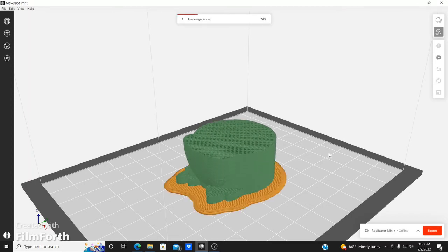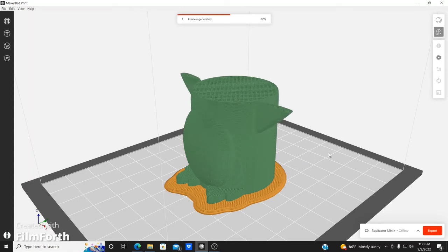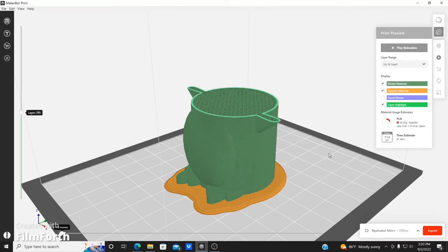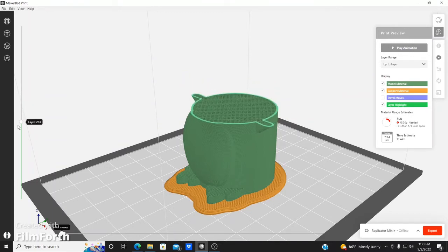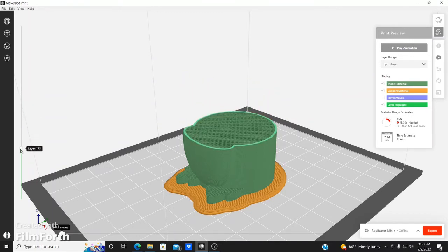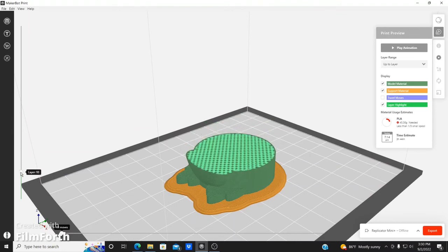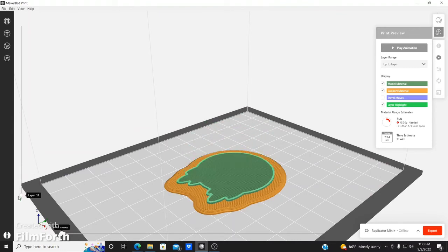There you go. So now this is what it looks like from the tool path and how it's being generated in a simulation. On the left, you have the scroller. You see layers of 295. If I was gonna do the entire full layers, it'll give me an estimate of about 590 layers of how far it'll print out. And then I can bring it down to see how well it's gonna print. This is important because you want to know how it's gonna print right away. If everything runs okay, you're good to go.